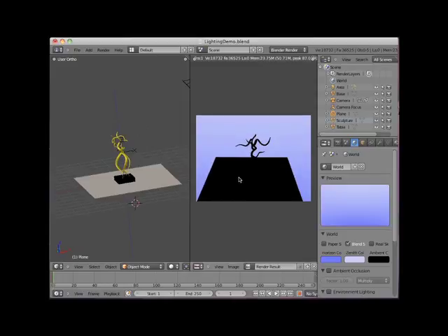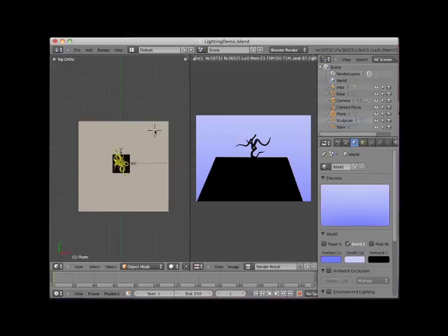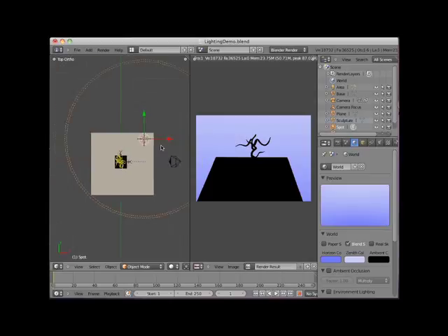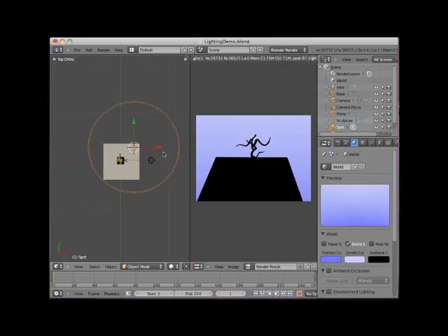As the scene has no lighting objects, the sky is displayed, leaving the sculpture, base, and plane in silhouette. I'll place my 3D cursor in the top view and add a spot lamp object. Notice that from top view, the spot lamp appears to be a circle of light. I will switch to front view. Here we see that the spot lamp is a cone of light emitting from a point.